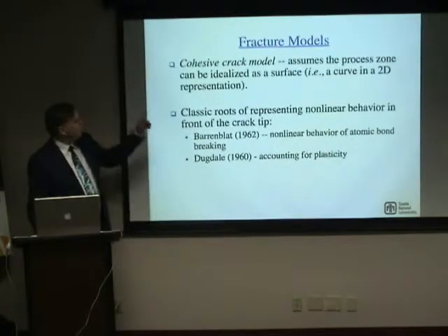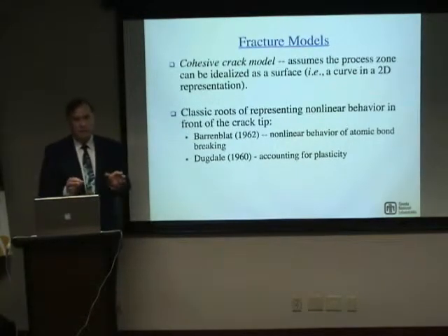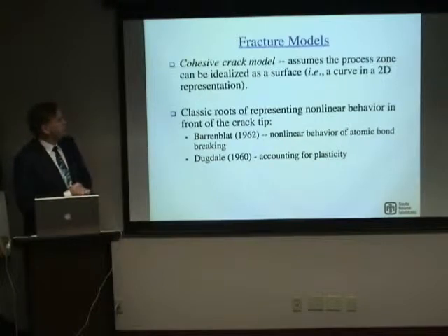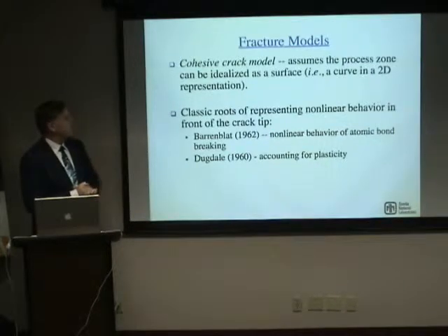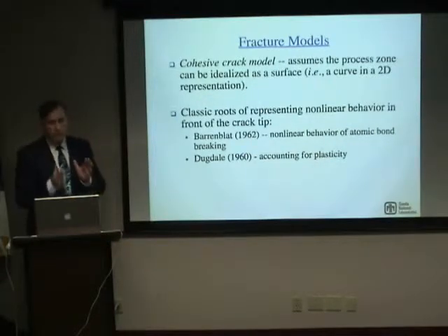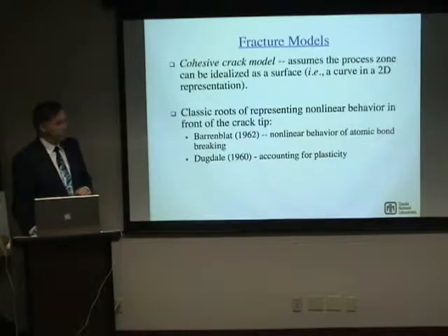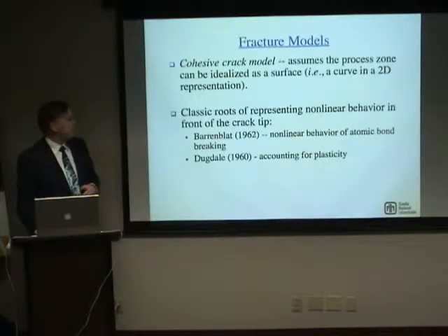So we're going to focus on the case where you can't idealize it as representing a point, and we're going to need to represent this process zone, but we're going to make another assumption, and that is we're going to idealize the process zone as a surface, or in 2D it's going to be represented by a curve. So we're saying all the inelastic processes will occur over this curve in front of what we would think of as the true crack tip where there isn't any bridging.